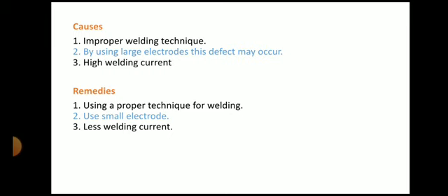Now what are the causes? Improper welding technique, then using a large electrode and high welding current. Remedies are using proper technique, using a small electrode and less welding current.